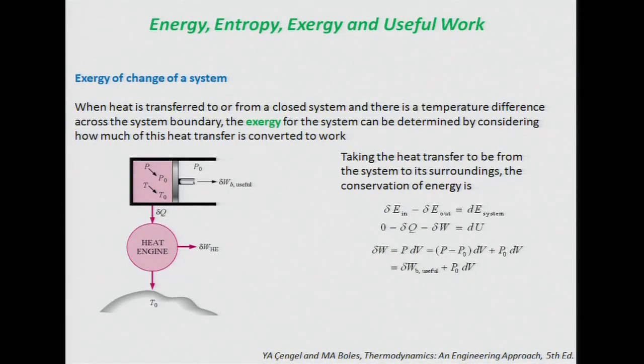Let's look at an exergy change in a system and go through it relatively slowly. I'll try to slow down a little bit here. So again, we'll go back to this little simple device. We have a piston, a heat engine, a reservoir here, and we're looking at the incremental works of these things. And we're looking at this heat transfer across here. When heat is transferred to or from a closed system and there's a temperature difference across the boundary, the exergy for the system can be determined by looking at how much of the heat transfer is converted to work. And of course, every time you do a real system like that, it's going to happen.